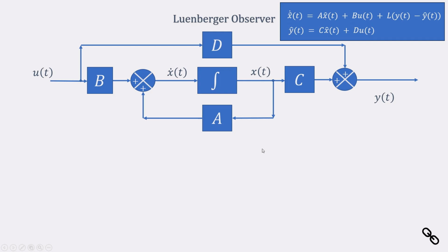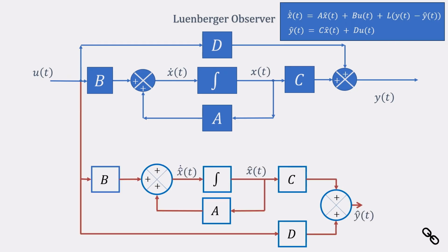So, if I have to look at a block diagram of how the Luenberger observer is designed, you can see that this is the system that I have, x dot equal to Ax plus Bu, and this is the actual plant. Okay. Now, this was the estimator, right, the open loop estimator. Remember, this is how the open loop estimator was designed. The problem with the open loop estimator was that if there are disturbances in the actual plant, the open loop estimator has no way of knowing that.